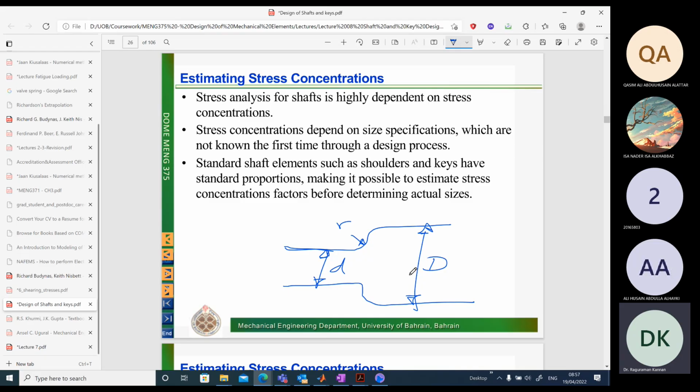So if we do not know any of these dimensions, what are the problems we could face when we come up with the equations? In the equations, if you recall, we used Kf, Kfs, which were obtained from Kt, Kts, and q and qs.